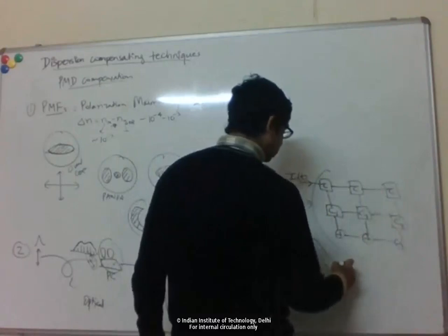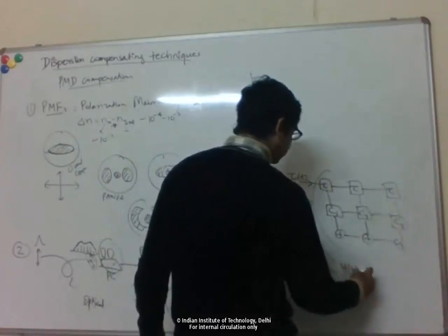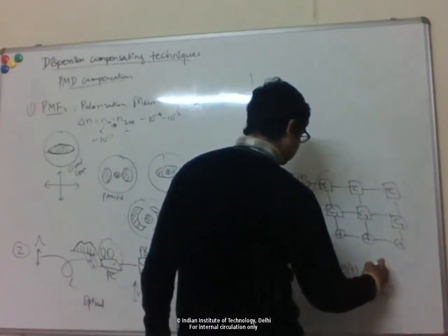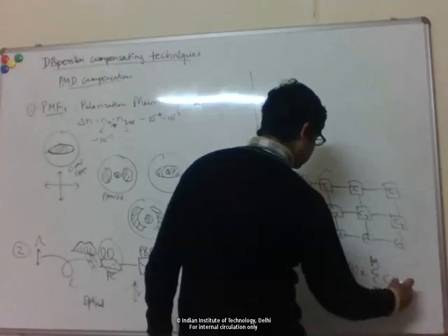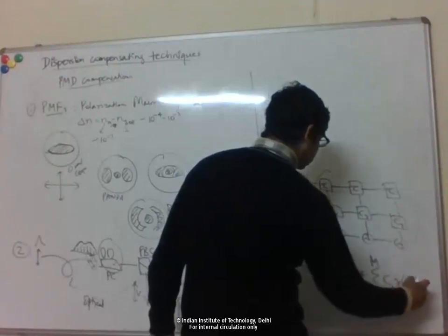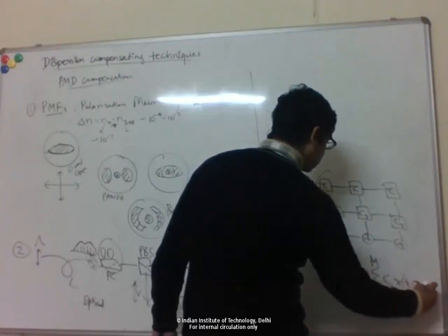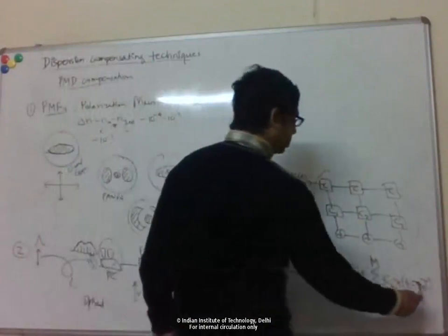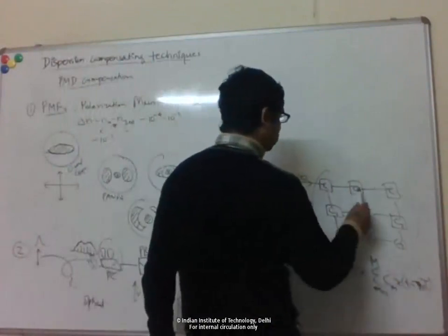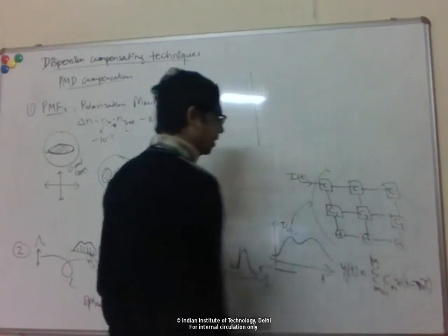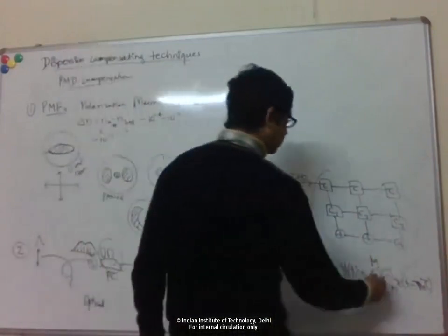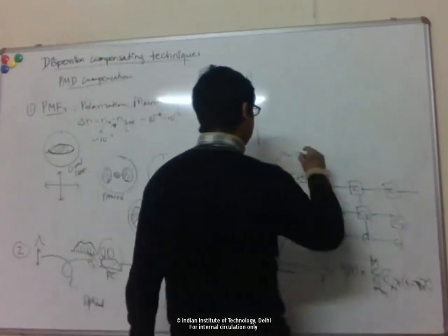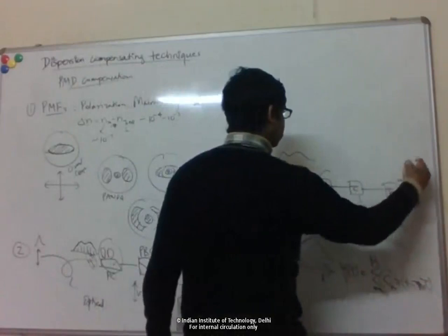So this filter response, your output, can be written as a summation over some m taps. Right, so it's like a tapped delay line, with delays tau, 2 tau, 3 tau, and you multiply each of them by some weights. Then you try to optimize these parameters, these coefficients, and the number of taps, such that after this filter, your pulse is sort of restored.